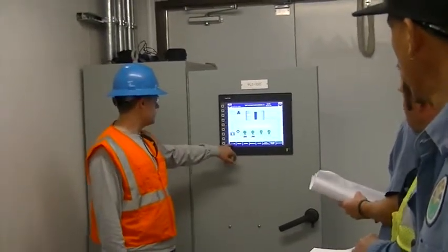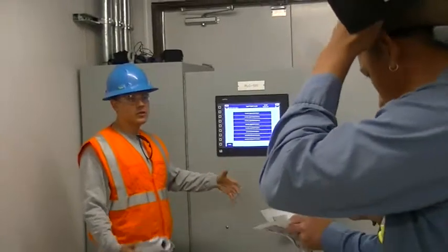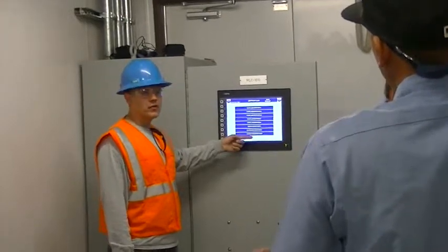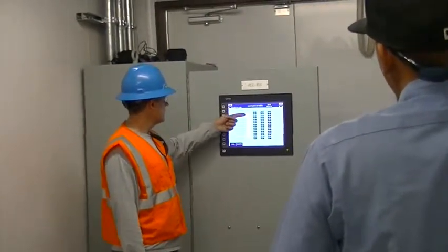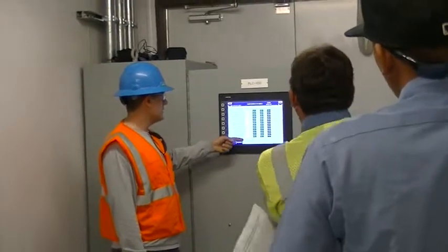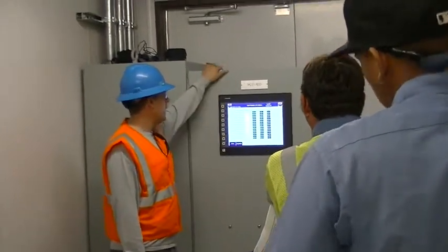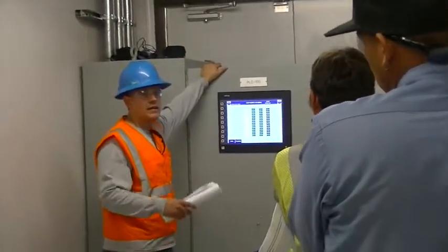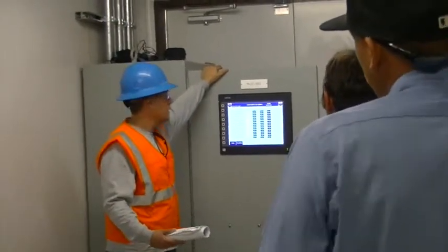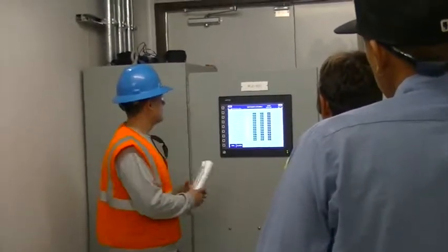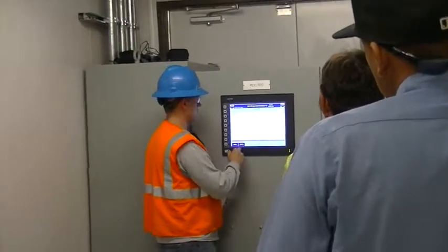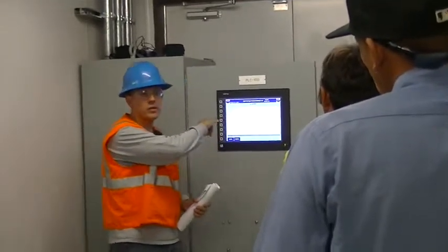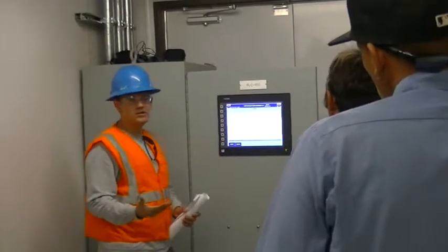Oh, there's one that I didn't go through. This Plant IO is what I use for troubleshooting. It shows you all your inputs, outputs, and your cards and what they're doing. So you click on them, and this will tell you the state that it's in, if it's off or on. Then it has a force enable and a force state, so that's overriding that in the logic, either on or off. When you do that, it'll pull up the alarm, and it'll also show you the force enabled on the alarm as well, in the alarms and events. So you can see what's been forced on or off.